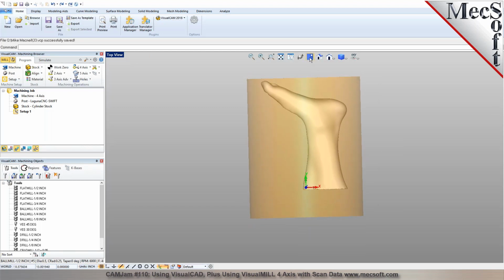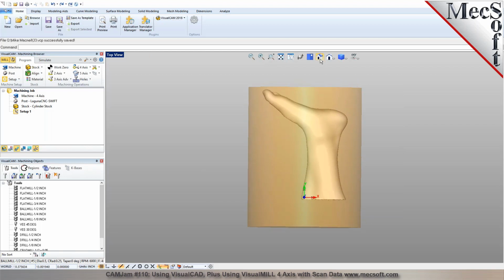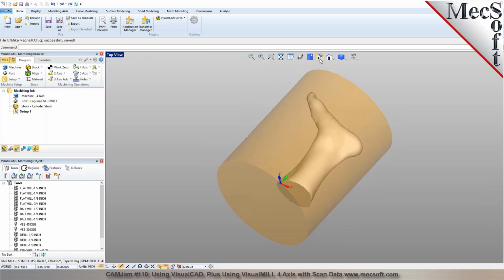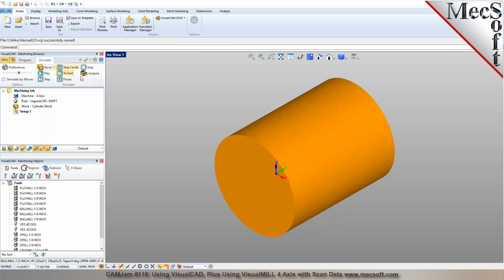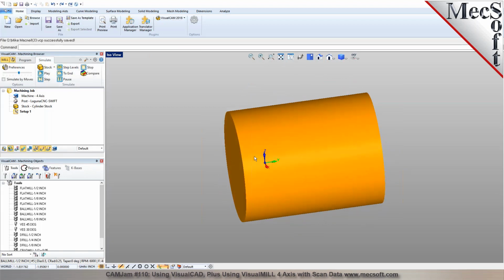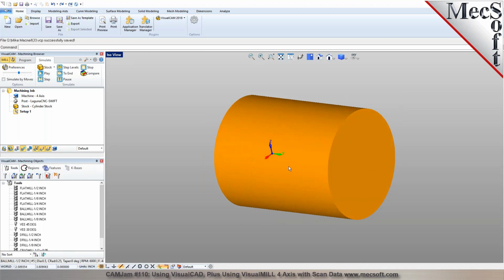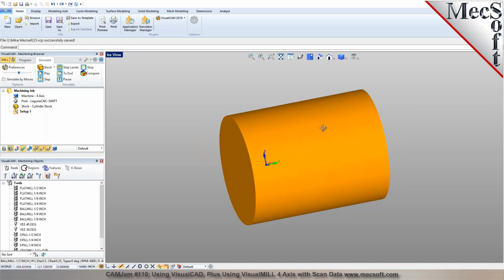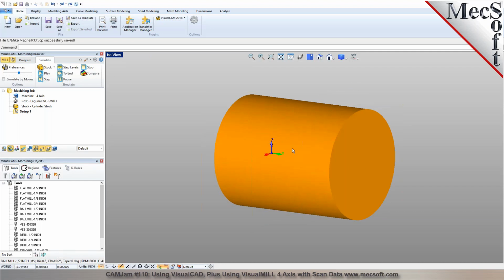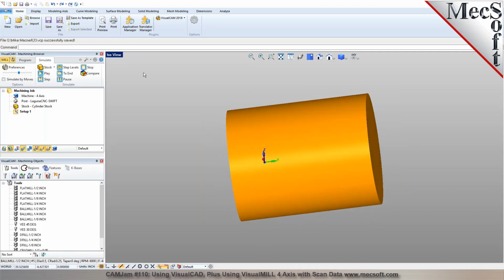Okay. Now the next step before we start programming this part, we want to make sure that we are establishing your XYZ origin, so you can do a touch off and then establish the rotation center correctly in here. Now, where would you like to place the origin on this blank in here? Would you want to put it right in the center line of the stock and then put it to the rightmost face or to the leftmost face in here? Or you want to put the 0 to the top in here? Yeah, I would probably say center. Center. Okay, center and center, or center and the rightmost face? I say center and center, yeah.